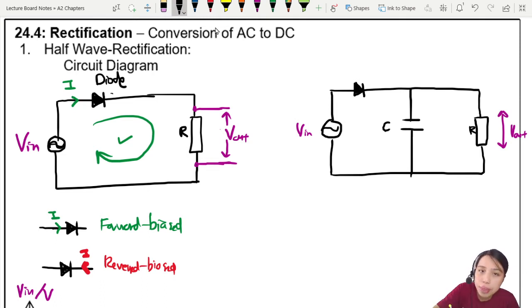Let's say in this first part, positive is here, negative is here. Does current flow through? Yes, current does flow through. So we have a current that can flow through the diode. Now when current comes here, some will go down to charge the capacitor and some will go over to this side. The capacitor will charge pretty quickly depending on its capacitance, but let's assume it's fully charged.